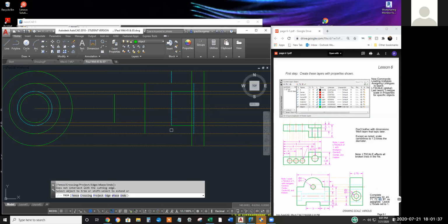That counterbore, the hidden counterbore, is a diameter of 14, right? By a depth of 12. Am I reading that correctly? Stand by. Depth of 12. I'm holding the textbook up. No, 7, diameter 17. All right, I see it now. Yes.